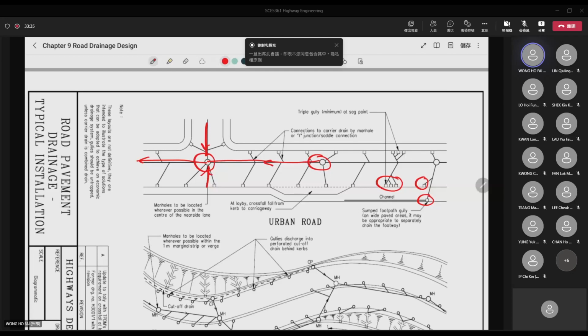So actually there are two kinds of drainage system. One is for wastewater, one is for rainfall, okay? So the one that you can see on the road basically is for rainfall. If you take a look at the advertisement from the government, they have already asked you not to put wastewater in the gully because they are just for the rainfall, okay? And for wastewater, there's another system to collect it, and the wastewater has to be treated before it is discharged to the sea.